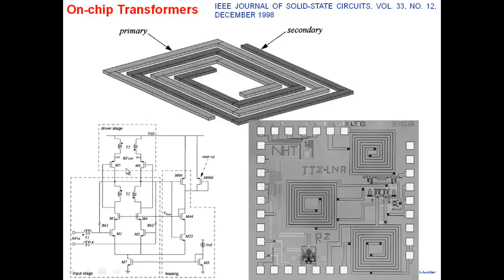realize that for many of these things, the fact that you can make it is important, otherwise, what are the alternatives? Think about what these people have been able to do, make a complete amplifier here, which requires transformers. If they're not using on-chip transformers, what is the alternative? You have a chip here, and then you have to construct an external transformer, right? 3 of them. And you can imagine the external transformers, their weight, their size, and how unwieldy it will become. So even the other solution is not a very attractive solution. A transformer there, a physical transformer, big one sitting outside. So even that is not a good solution.